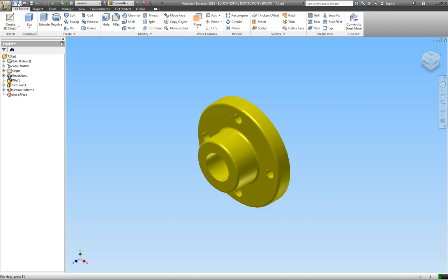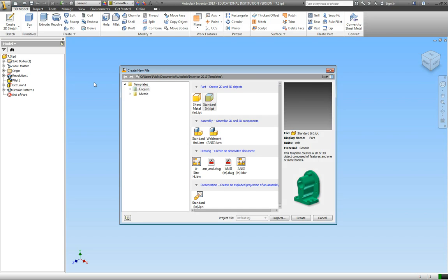So I want to start a new part. And how do we know whether to use English or metric? Well, the two things that are readily apparent in the text that this is an English drawing are that you don't see the word metric enclosed in a rectangle, which you should see if it's a metric drawing, and we also don't see the dimensions given in millimeters, nor do we see in the directions for the part in the text that it says construct the part in metric.